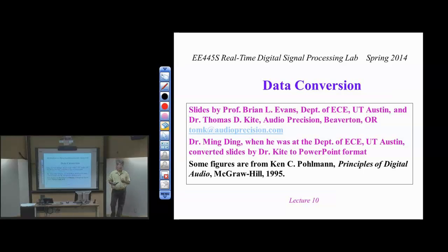We sample and quantize that, so we take the current and voltage from the transducer, which is in continuous time and analog, and we pass it through an analog to digital converter to sample and quantize that information. Now we have a digital discrete time stream that we can process, compress, and otherwise embed in this video as you're watching.